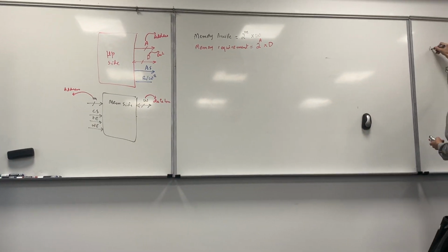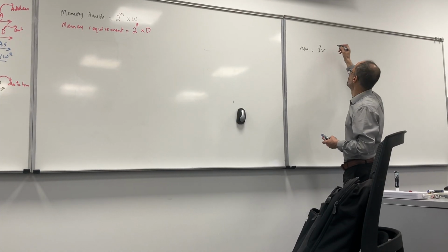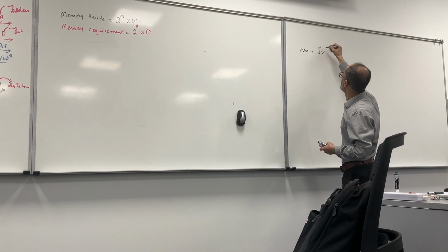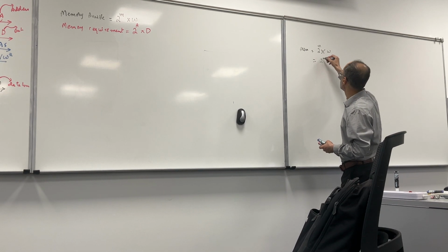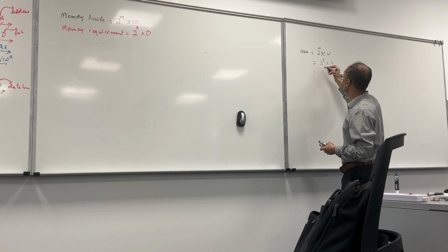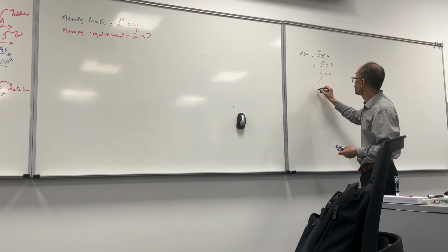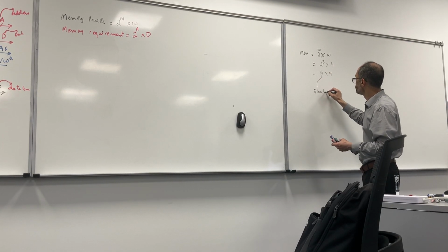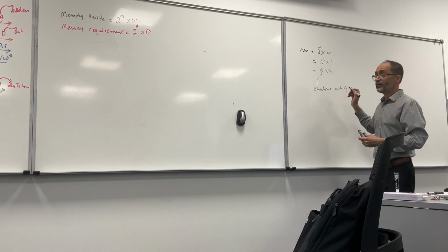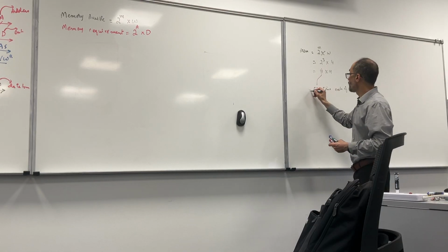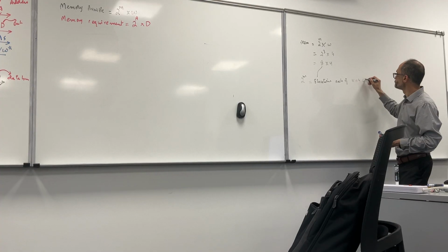The memory available will be 2 to the power M cross W. What is M? M is 3. 2 to the power 3 cross W, which is 4. 2 to the power 3, how many locations do we have? We have 8 locations, which is 2 to the power M. Each of how many bits? W is equal to 4 bits.